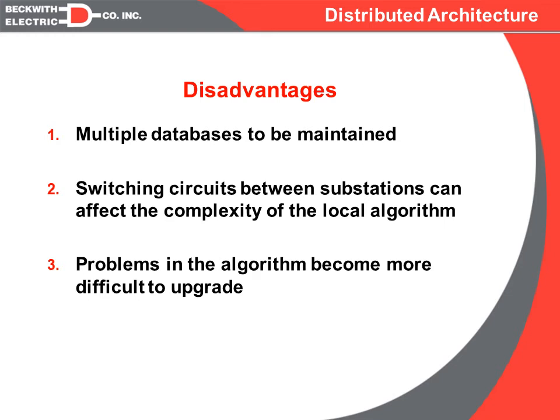The other problem is, again, with sectionalizing. Typically, the system is set up to look at the regulators and capacitors that are typically on the radial feeders of the circuits leaving that substation. If there are normally open ties to circuits feeding other substations and the circuits get reconfigured, some of the capacitor banks on this particular substation will move to another, or vice versa, and typically these distributed systems cannot handle that, and typically they will have to be closed down when that abnormal switching occurs.